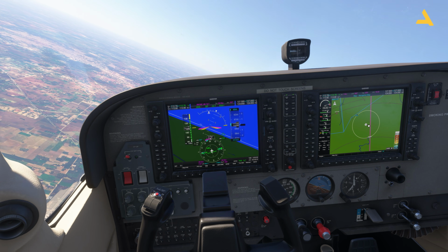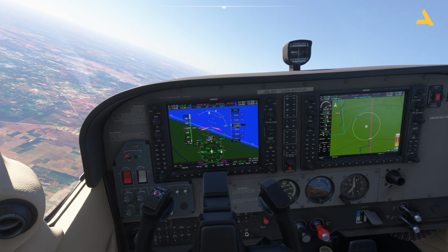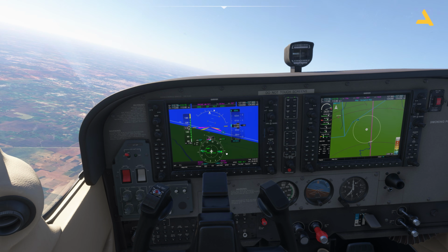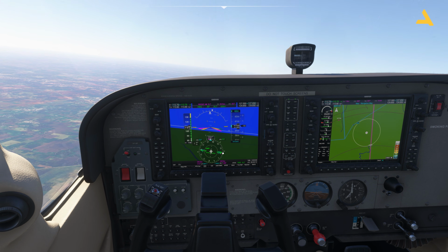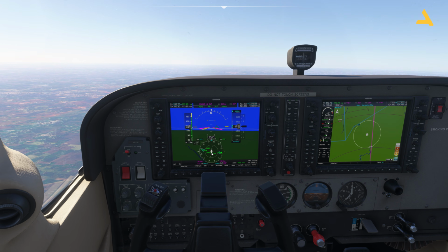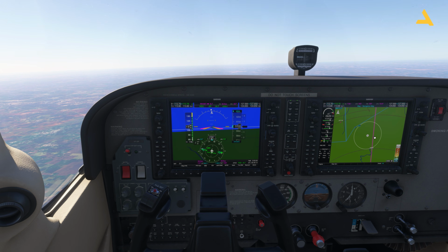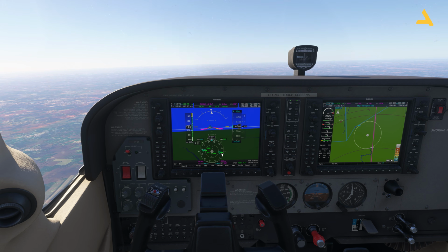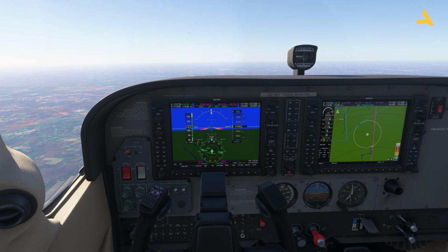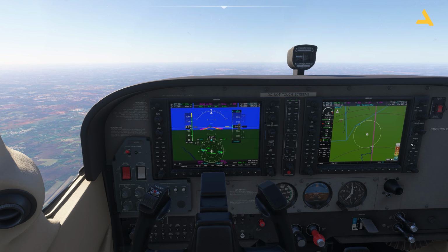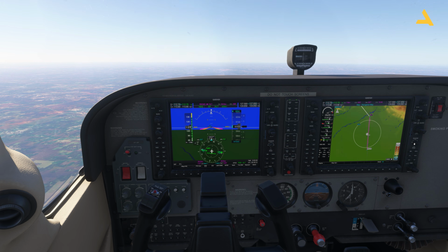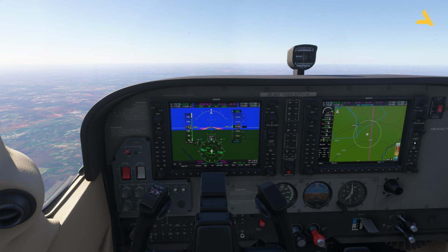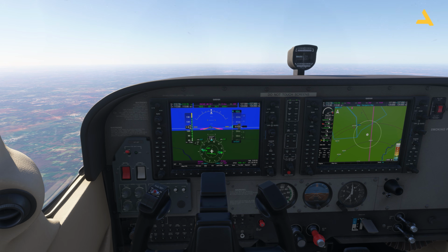And now you can see I'm going almost opposite. So my course is here, 355 degrees. And now you can see that this deflection has started to appear. Now what's happening is this: as I'm now away from the Lahore VOR, that's why this deflection is very little. But there is deflection. So that's what I was telling you, that the VOR's accuracy decreases over the distance. So although you will keep on tracking it, the accuracy will decrease.